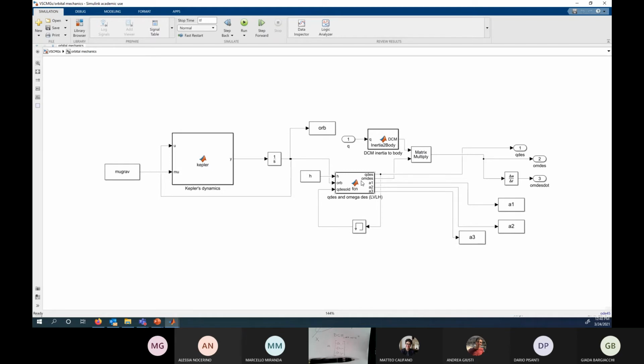This is me taking the position of the satellite and operating on those vectors and creating these other quantities. So I know what they are, and they're not in principle measured other than R eventually, but that will be filtered. So it's not noisy signals that I'm feeding into the derivative. But in general, if you have noisy signals, things coming from sensors, for example, it's usually a bad idea to use derivative blocks and numerical derivatives. But in this case, it can be done, okay?